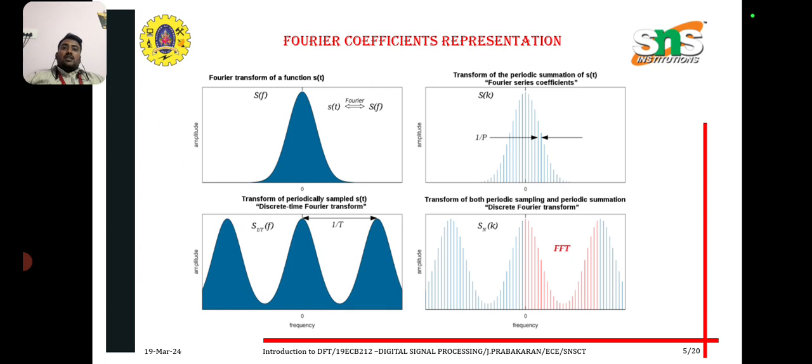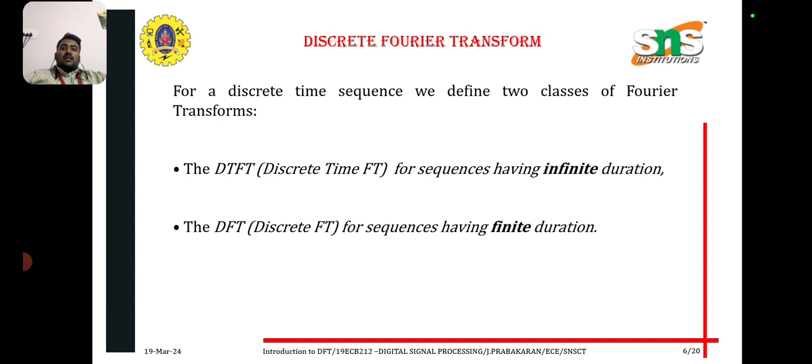And data compression. Techniques like the fast Fourier transform, which efficiently computes the DFT, are widely used in data compression algorithms. For example, in audio and image compression, DFT based methods such as MP3 and JPEG use frequency information to achieve compression while preserving perceptual quality.